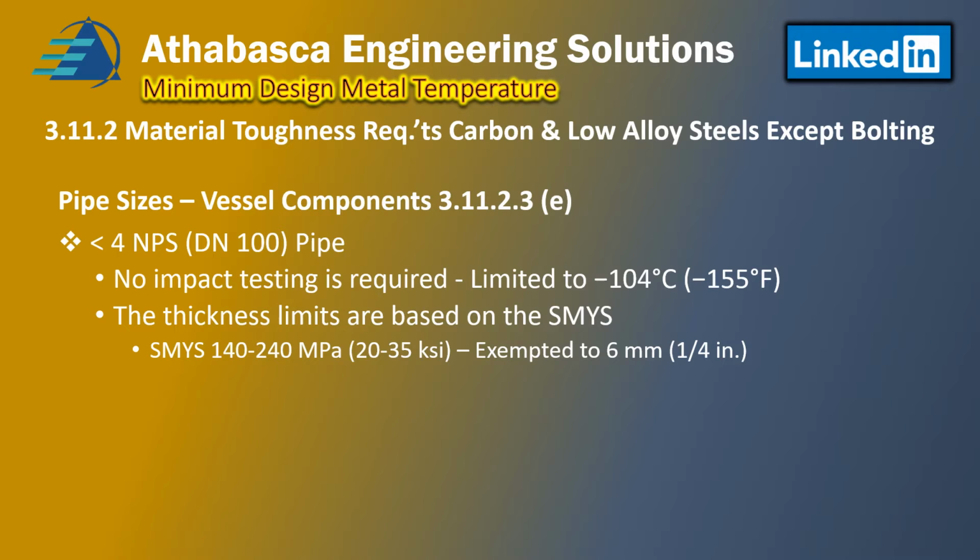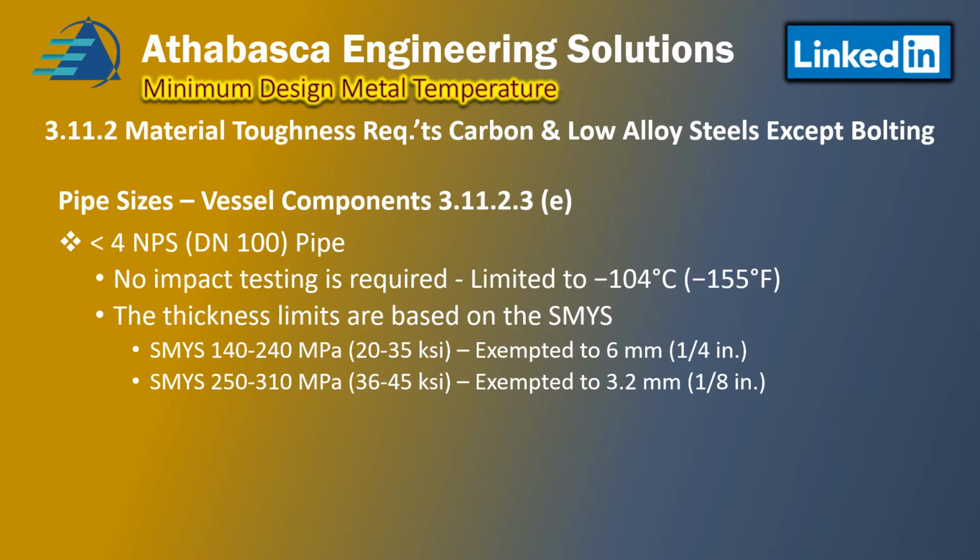Basically, if you have a yield strength between 20 and 35 KSI, then you're exempted up to 1/4 inch in thickness. And if your yield strength is between 36 and 45, then you're exempt to 1/8 of an inch. You can see how as your yield strength increases, the allowable plate thickness before you have to get the exemption drops.